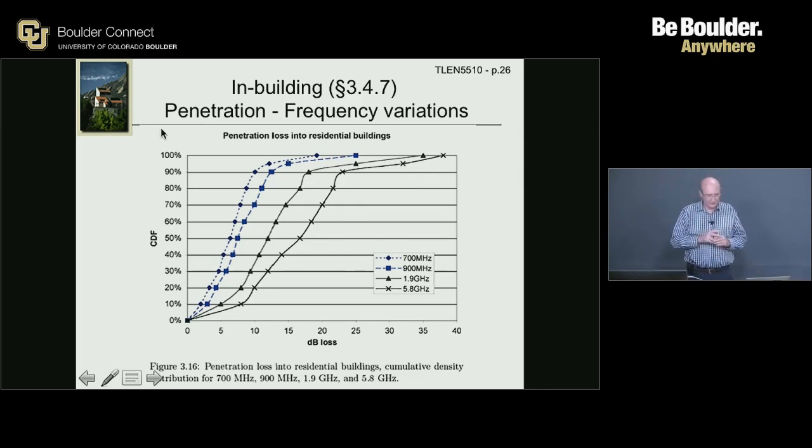Now, this is all things being equal. I'm not looking at various angles of incidence, etc., because it sometimes is nice to have a model that just gives you an arbitrary value. If I had to take an arbitrary value, I'd say, all right, I've got a propagation model, I can use Hata or something like that. It'll tell me if I have a base station that's 90 feet in this suburban area, it'll tell me my coverage. That's fine if I want to put a device on everybody's home.